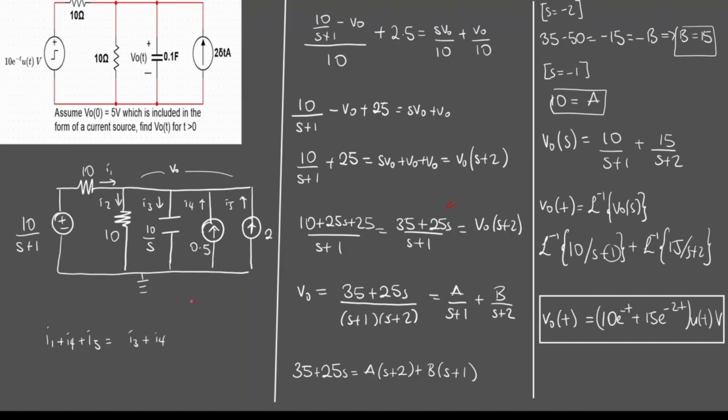Okay, so that's going to be your capacitor in parallel with a source going up. Okay, and the value of this is going to be CV0. So it's important to remember the polarities of this and the values of this, because for inductors the current source goes down. Alright, so that's what we have to do when solving circuit problems with Laplace transform.